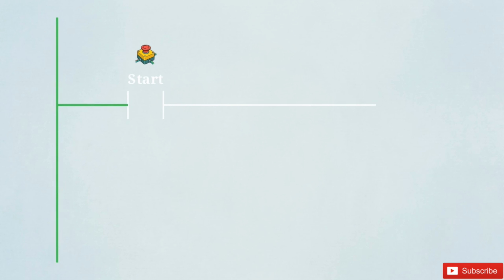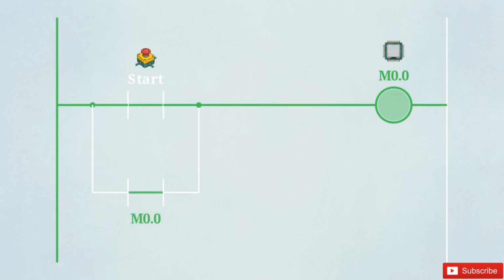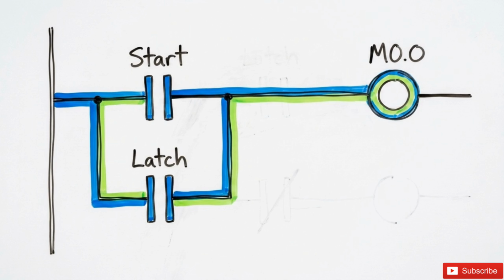Insert a normally open contact to represent the physical start button. When this button is pressed, it allows logical current to flow into the rung. Link this contact to a memory coil labeled M0.0. We add a branching latch beneath the start contact, so the system stays active even after the physical button is released. Network 1 now serves as the system's memory, providing a continuous internal signal that the rest of our logic will use as a prerequisite.